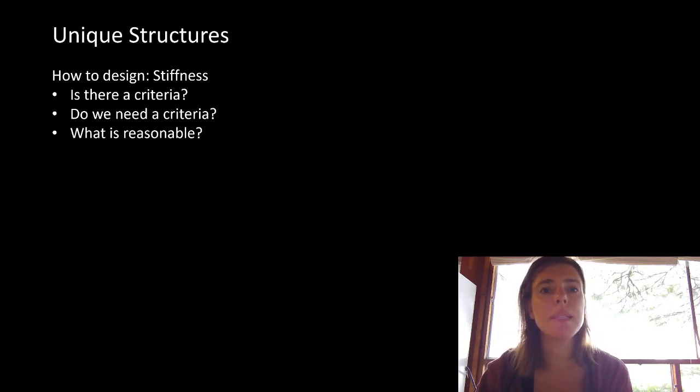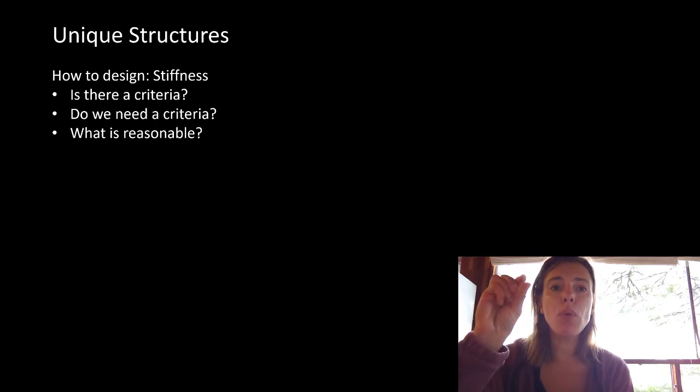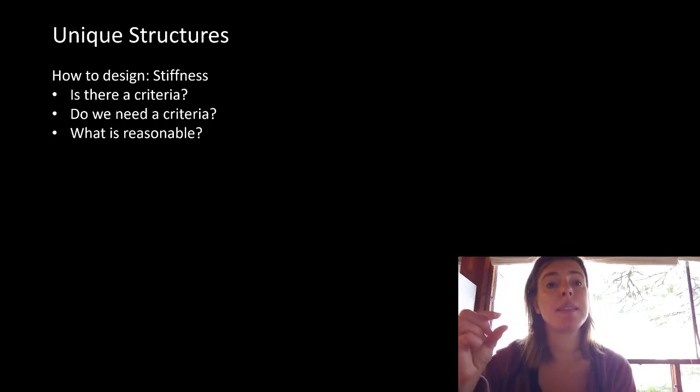But sometimes it's unreasonable. An art structure, for example, that has nothing that can be damaged on it and a person's going to hang on it, who cares if it moves enough or deflects enough that they're uncomfortable? They'll let go and get off. As long as that doesn't cause any permanent damage to the art piece itself, what does it matter if at that moment it moved 10 millimeters instead of only the 7 that might have been code prescribed? We don't care. There's no damage coming from that additional 3 millimeters of movement.